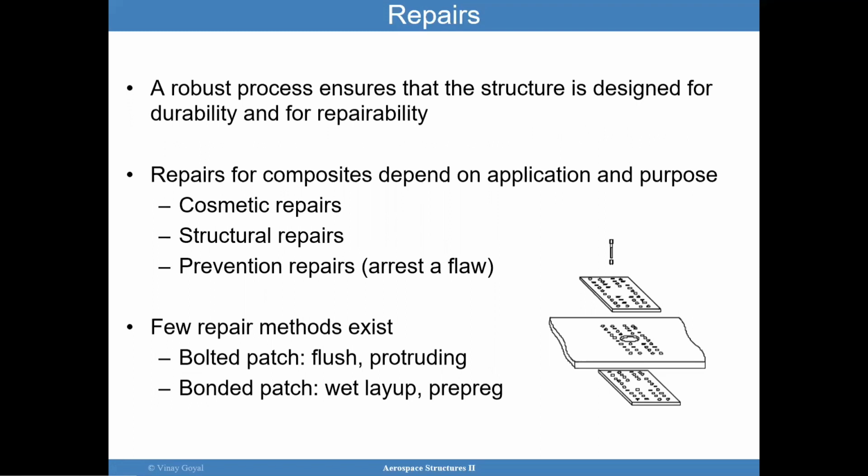Repairs for composites depend on what we're trying to accomplish. It could be just a cosmetic repair, a structural repair, or a prevention repair, so to arrest the flaw. I'll show some examples later on. Few repair methods exist, so you have the bolted patch or the bonded patch. So two approaches there. On the right-hand side, I show more of a bolted patch configuration.